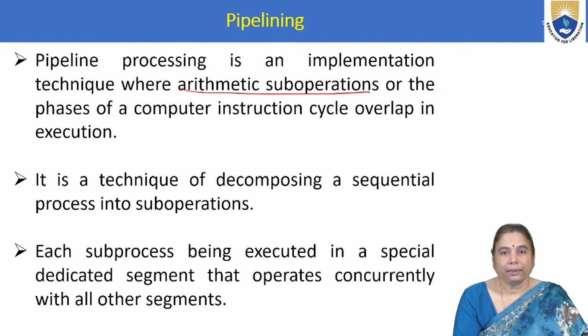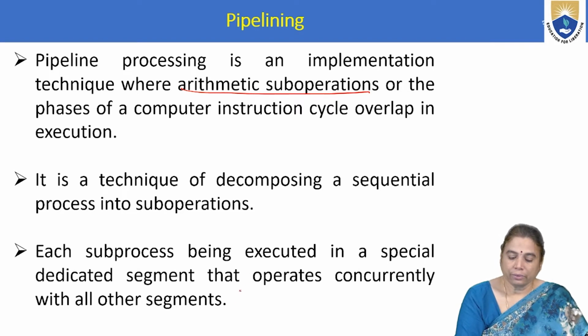So the pipelining technique decomposes a sequential process into sub-operations. The computational task can be divided into small parts. Each sub-process is executed in a special dedicated segment that operates concurrently with all other segments. So here each sub-operation can be executed in a segment, and these segments can operate and share data among other segments during execution of the instruction.